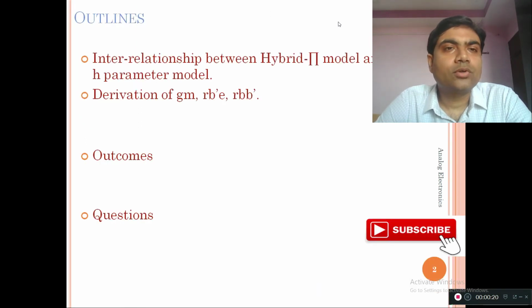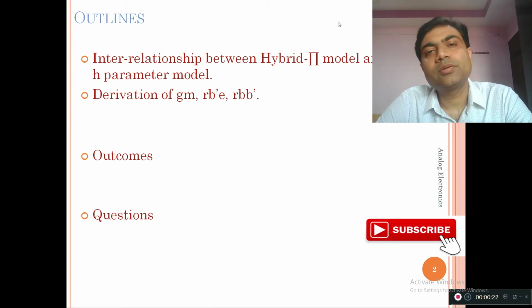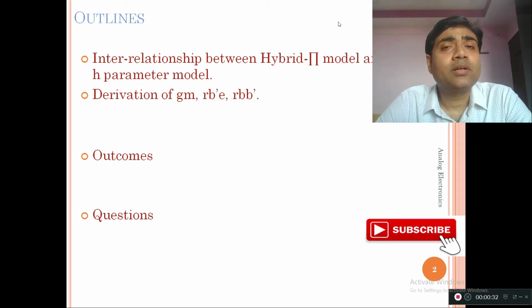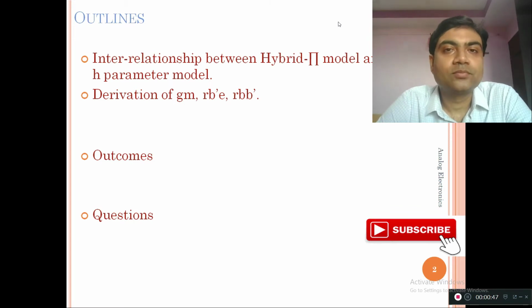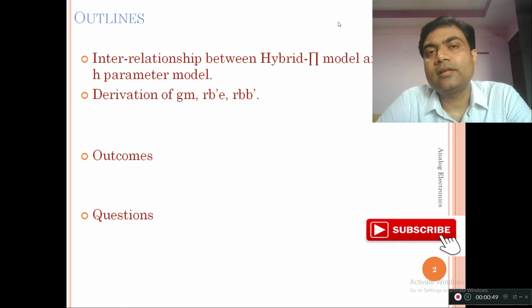So the outline of today's lecture is the interrelationship between the hybrid pi model and the H parameter model. We draw the hybrid pi model for the high frequency analysis of the amplifier, but it does not mean that we cannot analyze low frequency amplifiers using it. Today we will see how the hybrid pi model can be modified to analyze the amplifier at low frequency also.